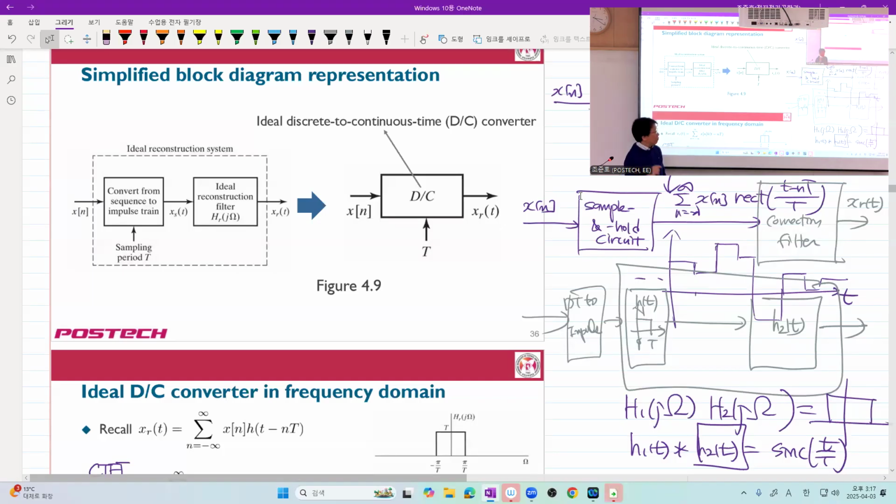Okay, this is very important. Just draw in the frequency domain, and what will happen? This one, in the frequency domain, is a sinc pulse. And this one needs to invert this part and needs an ideal something. So what I remember correctly is that this correction filter has a frequency response something like an inverse sinc with brick wall fall-off, with proper scaling.